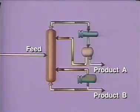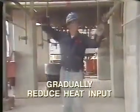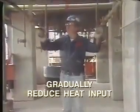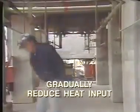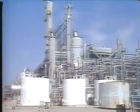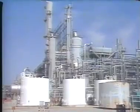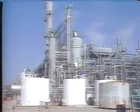At this point, no feed is being added to the column and no products are being withdrawn. The material that remains in the tower continues to fractionate, but is not removed as product. The next step is to gradually reduce the heat input to the tower. In vacuum columns, the vacuum is taken off and the column is shut down under atmospheric conditions. As the temperature in the tower decreases, light components fall to the bottom of the column and mix with the heavier material. This liquid mixture is pumped out and saved for reprocessing.